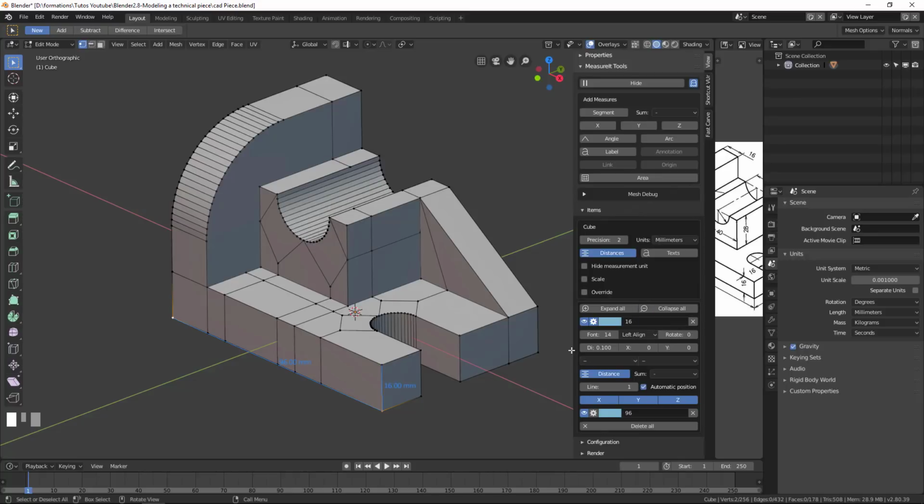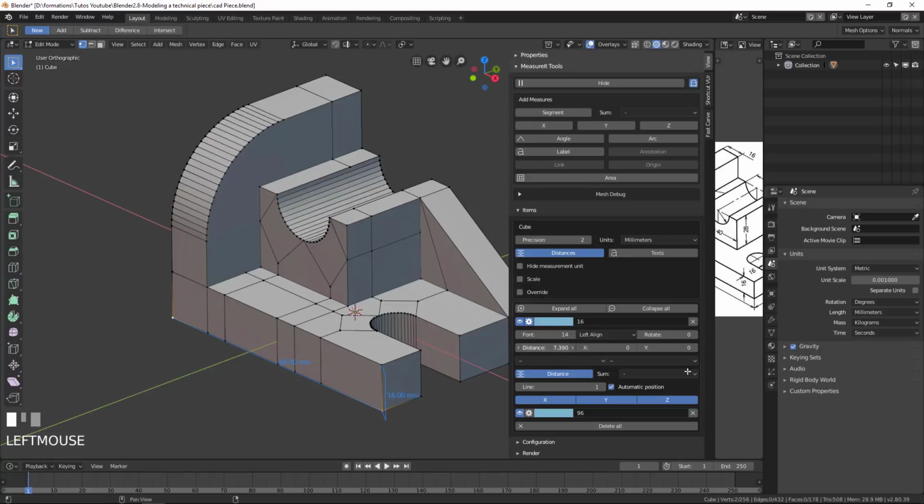You have the possibility to increase the distance if you want, and to increase or decrease the distance on the X and the Y axis of the text only. Okay, you can use a simple line or a triangle or T-shape. I will use a triangle. It seems more like an arrow. It's more visible for what I see. I prefer to do it like this, and a size of 8 will be better, I guess.